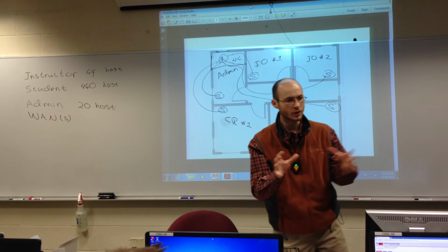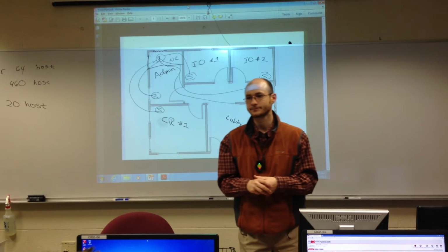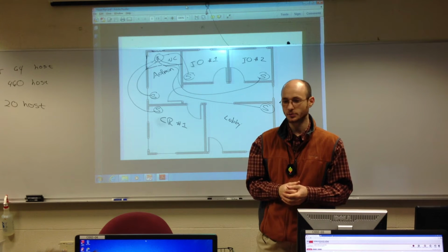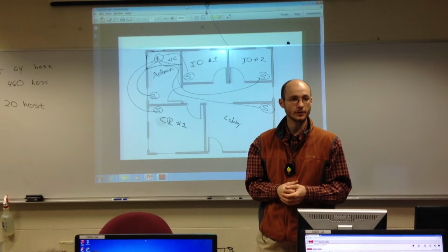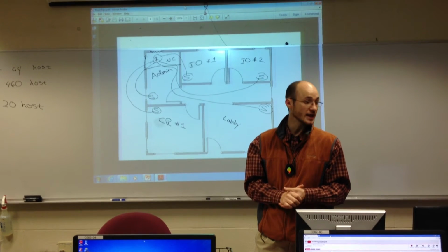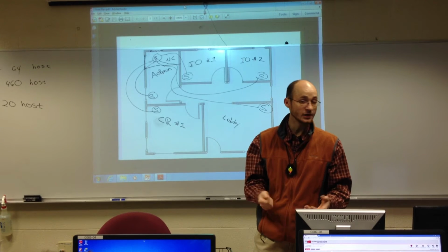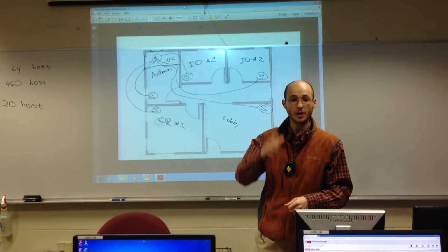Why don't you want it to fray out a little bit in the middle? It's going to get stuck. It's going to be a pain in the ass to troubleshoot later, all right? It's going to wrap around things. It's going to get tangled around itself. So after so many feet, either use a zip tie or black electrical tape, bind them up, and keep it going.